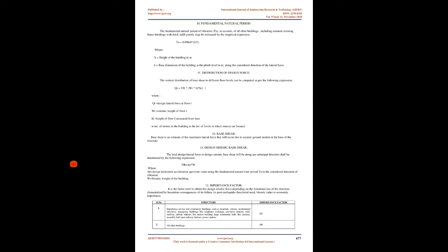4. Definitions. Terminology for earthquake engineering of buildings. 1. Earthquake. Vibrations of Earth's surface caused by waves from a source of disturbance inside the Earth are known as earthquakes. 2. Intensity. The severity of shaking of an earthquake as felt or observed through damage is known as intensity. Areas having the same intensities are then enclosed by contour lines. Such a map is called an isoseismic map.